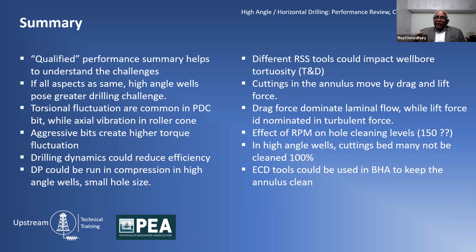It is also very important to understand that, unfortunately, the experience of the directional driller starts playing a role here, which cannot be quantified, because an experienced directional driller uses the natural tendency of the drilling tool and lets it float in the drilling window instead of causing too many downlinks, too much orientation with the rotary steerable.